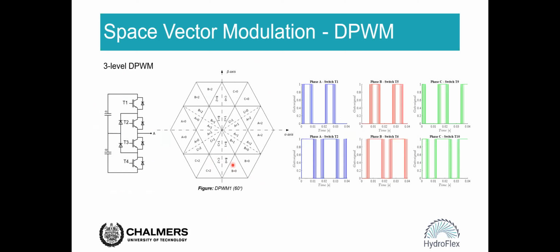However, if we look at the voltage vector hexagon of the three-level converter, it looks like this. And the first step is we need to determine in which region or which zone we want which phase to clamp to which state. So as we talked before, there are three states inside each phase, so state 2, state 1, state 0.